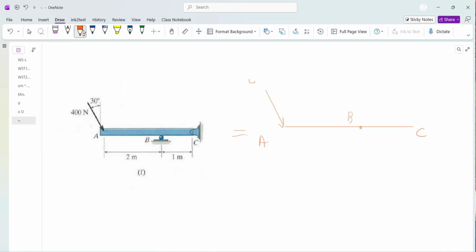That is 400 Newton. But because you opened up, you freed that reaction, what used to be an internal force. There was a B acting from ground to the bar, one from bar to here, so action reaction, they were canceling each other as long as they were internal. But when you release or free that, one of the pairs remains, which can be interpreted as exposing the internal force to external.